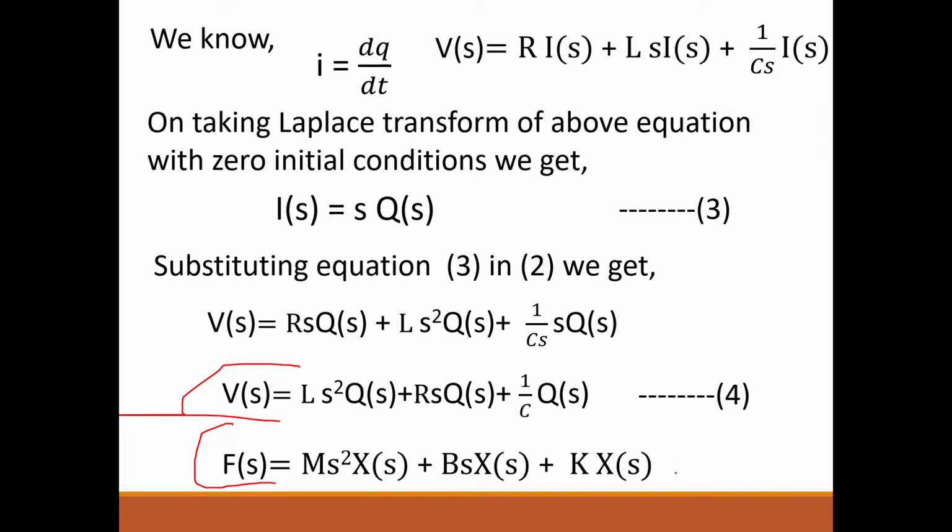So when we replace current with charge, we are getting the electrical equation, of course in Laplace form. When you compare the electrical voltage balance equation in Laplace form with the force balance equation in Laplace form, both are similar to each other, isn't it?